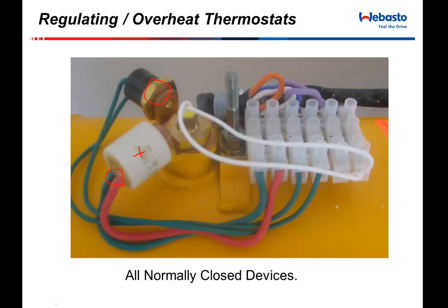you have an issue where we're heating just the water inside of it and it's not being moved. The unit will just start short cycling itself. Eventually what happens is you will create a small air pocket in there. You'll get the water temperature, which will spike up and will turn that thing off.